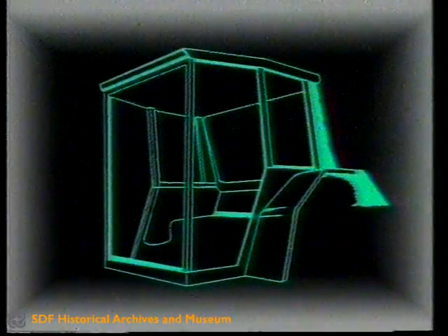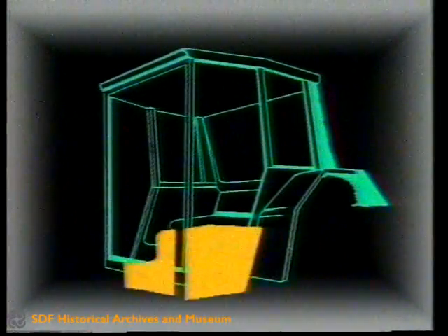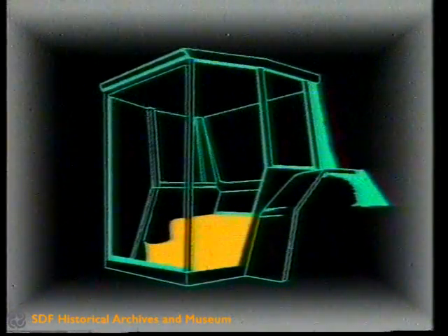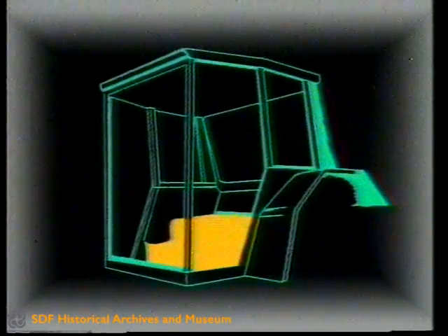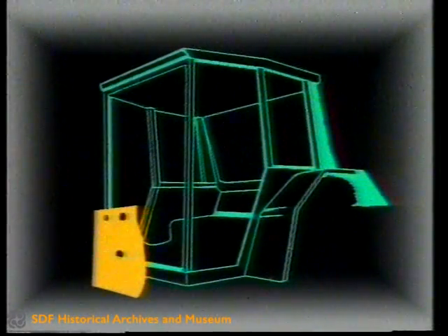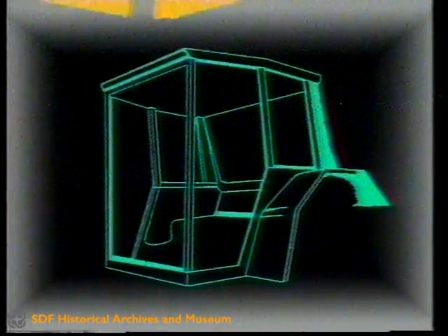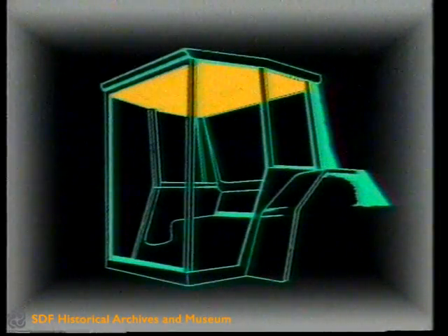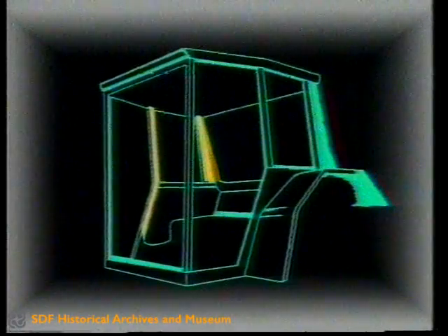Soundproofing of the platform has been achieved by a triple layer comprising a hard rubber matting with anti-slip relief finish over bituminous rubber and a foam material with high sound-absorbing qualities. Furthermore, a thick insulating, sound-absorbing partition prevents heat and noise from the engine penetrating into the cab. Finally, the lining of the inside of the cab walls is in sound-absorbing materials used in automobiles. Even the molded instrument panel is in sound-absorbing, expanded polyurethane.